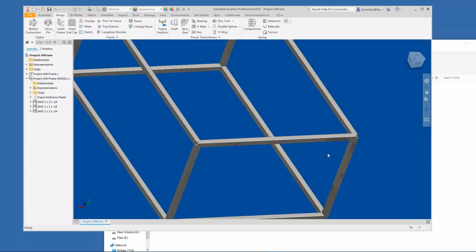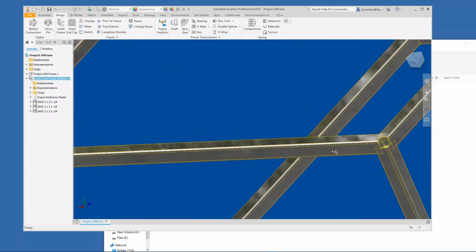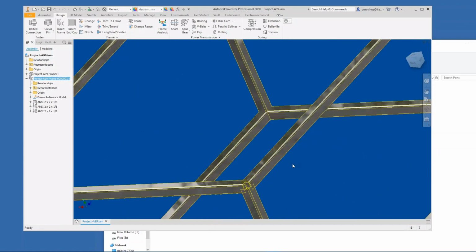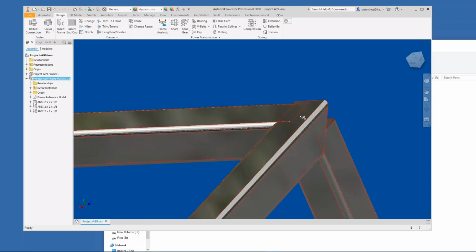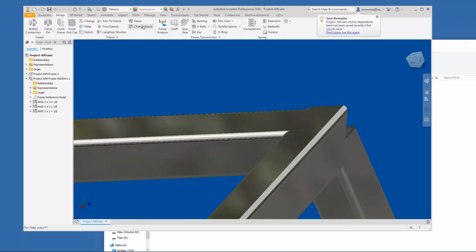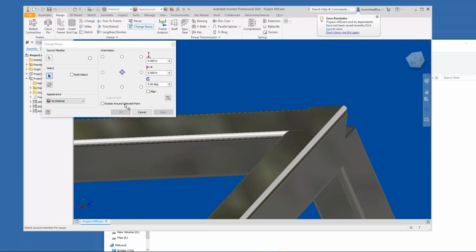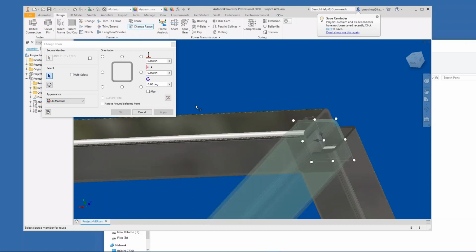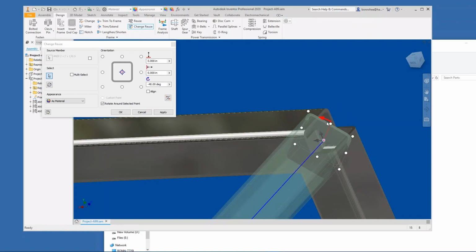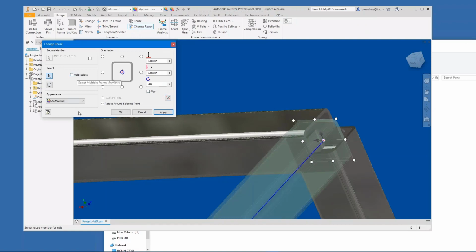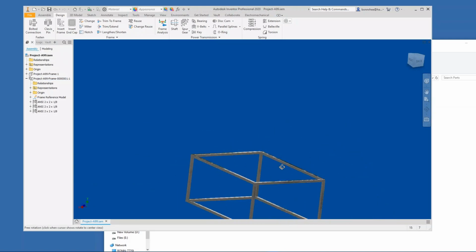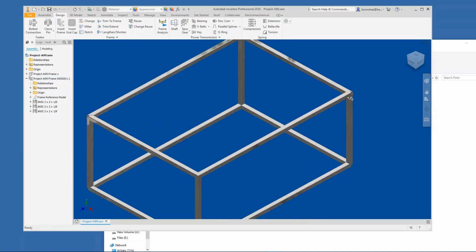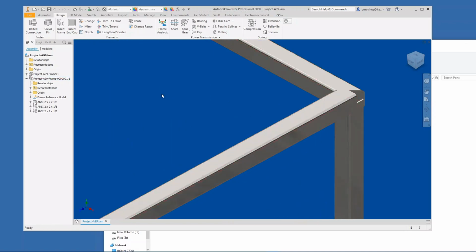Okay, and same with this end here. You can see this one needs only a 90-degree turn. So we go to change reuse. We select the member. And again, if you don't know if it's plus or minus, you can use the grips. This way is still minus. Okay. And now I need to finish the other end.